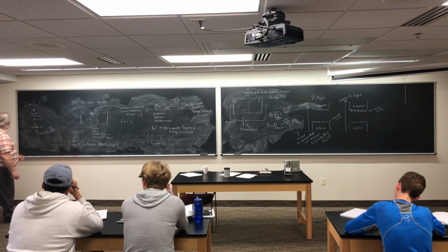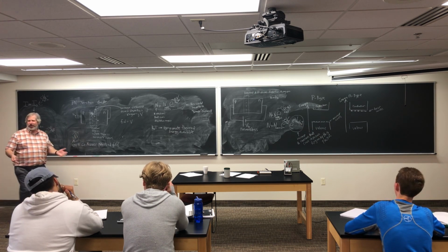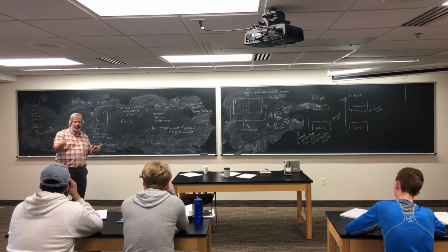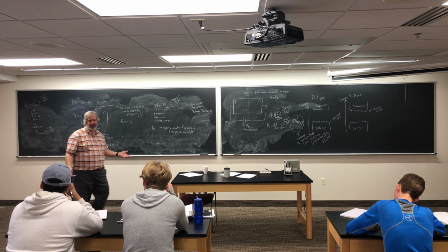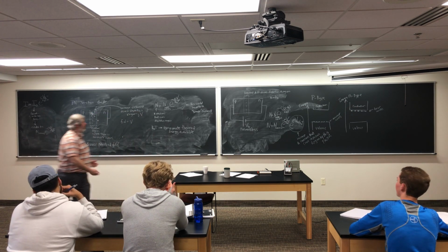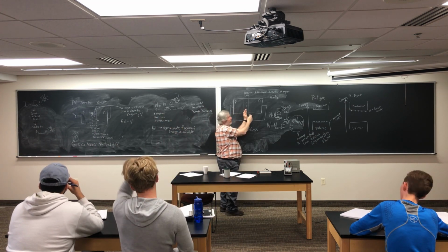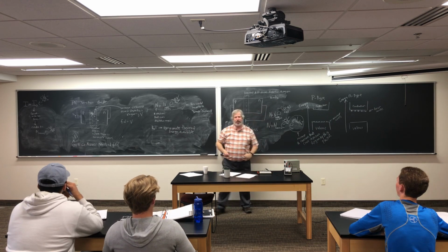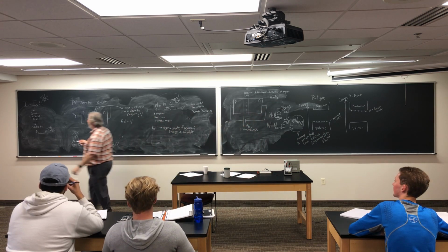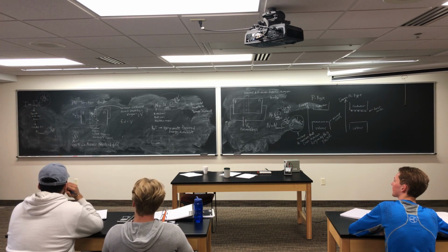So I'm not saying that this ratio, number of carriers e to the negative V over kT, is a current. We're saying it leads to a current. And let's call that current, just by them being able to randomly jump over once in a while, let's call that current I naught. And then I'm saying now by putting the voltage across that, we're reducing the voltage they have to cross by that bias voltage. So looking at the math, what we're really doing is increasing the current by that factor.